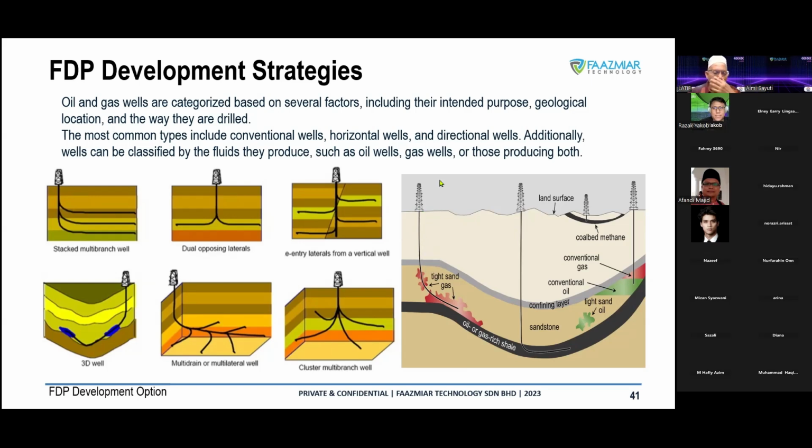I wonder whether the drill can be steered. Of course, with the technology nowadays, we always go for steering. We call it the RSS tool, a rotary steerable system, where we can steer even while rotating. It's a technology that helps us reduce tripping for correction runs and reduces errors and difficulties in steering, because with the steerable system we manage to do the correction almost immediately.